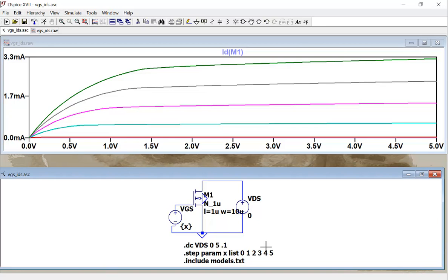So these are, you got a 2 or 1. 2 here, right? What are the 2 voltages? The red one, the other purple one. 0 and 1. Was that 1 volt not high enough over the 0.8 volts? It's just 0.2 volts bigger than 0.8. You can see it's just barely on. Current is low. So which means if you have a bigger VGS, you got a bigger current.